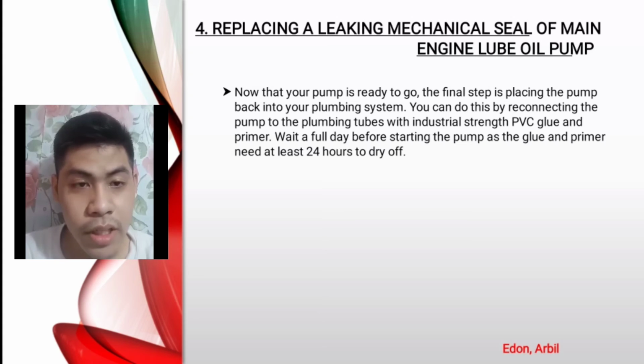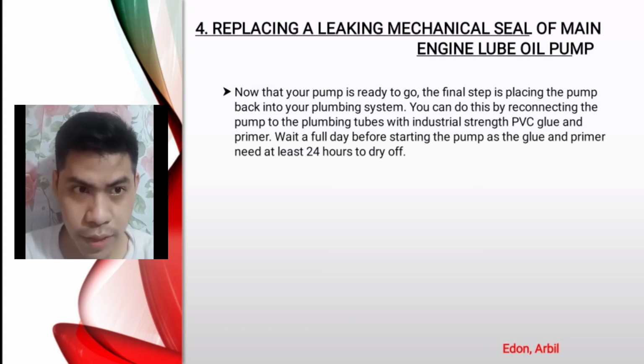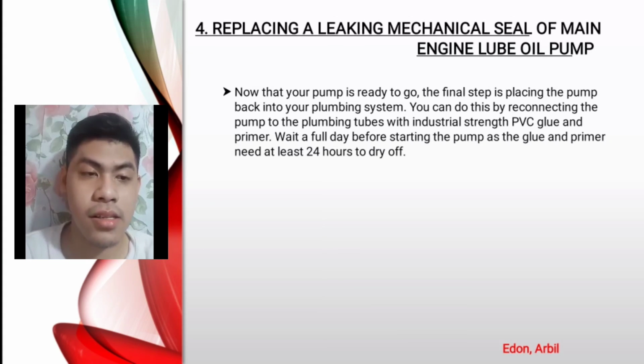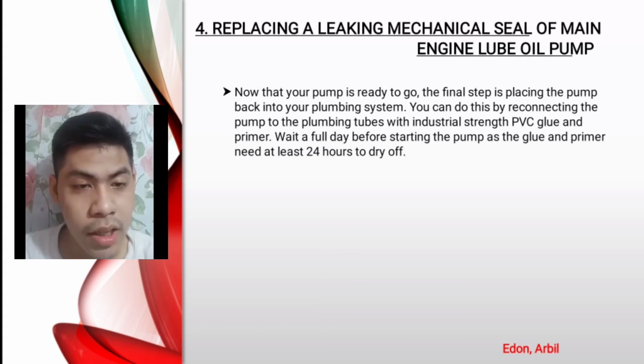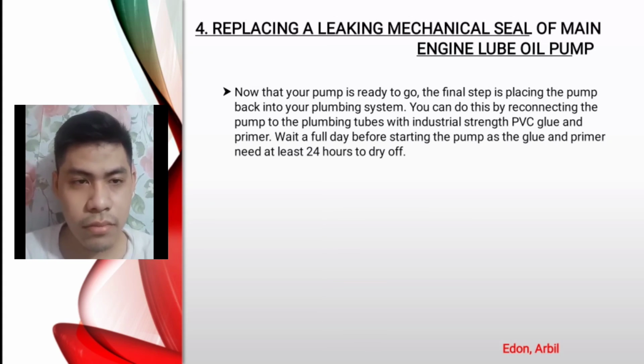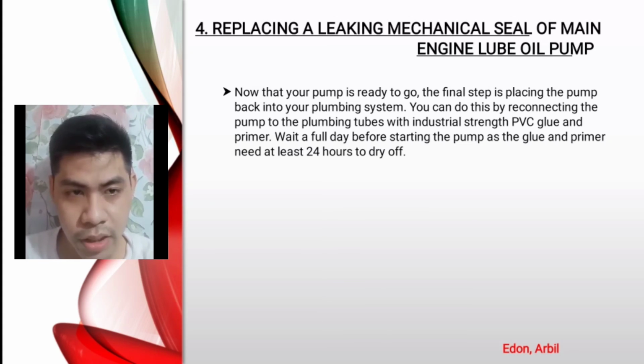Now that your pump is ready to go, the final step is placing the pump back into your plumbing system. You can do this by reconnecting the pump to the plumbing tubes with industrial strength PVC glue and primer, and wait a full day before starting the pump, as the glue and primer need at least 24 hours to dry. And that's all for replacing a leaking mechanical seal of main engine lube oil pump.